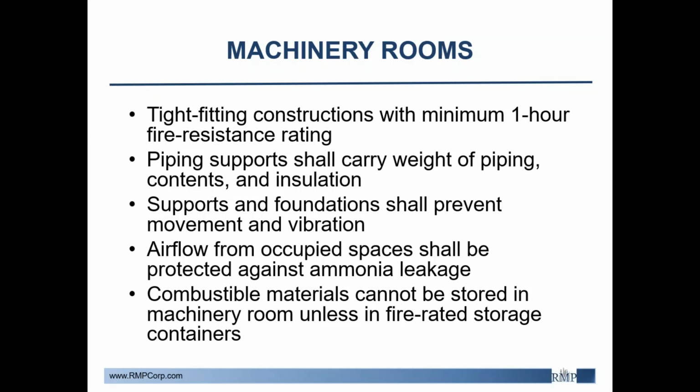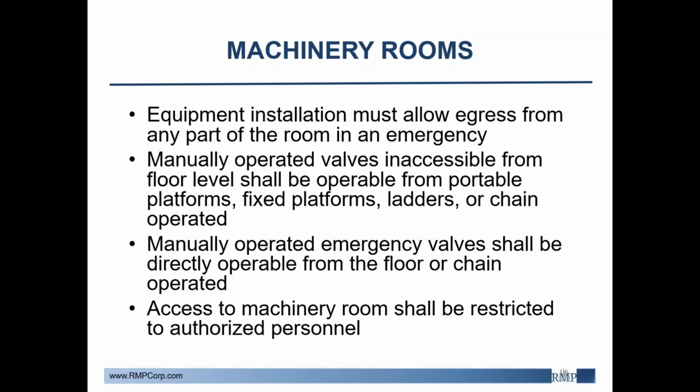Piping supports, again, California, we've got seismic issues, but generally speaking, anywhere, having those proper supports and proper materials, having that evaluated by a civil engineer if you can, or confirmed in the drawings if it's a newer system. As far as airflow, you basically don't want ammonia to leak into your occupied spaces. If possible, containing it in the machinery room and away from the rest of your facility. And combustible material should not be stored within the machinery room unless it's properly stored. And this, again, all goes into best practice.